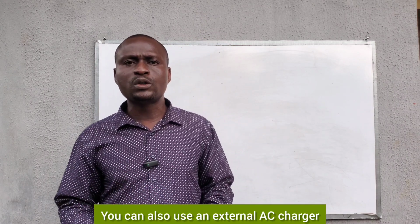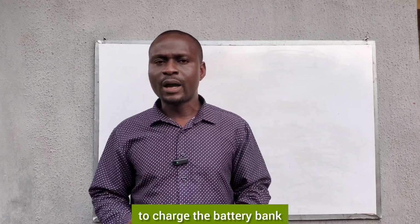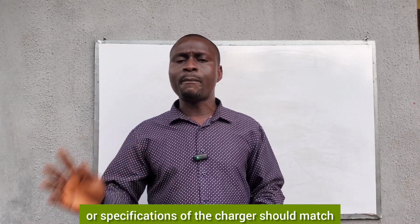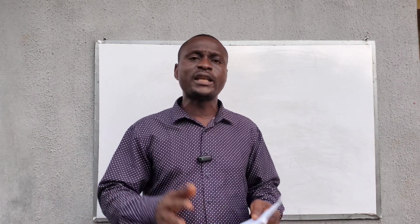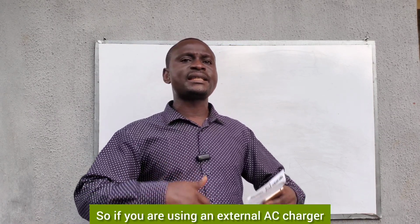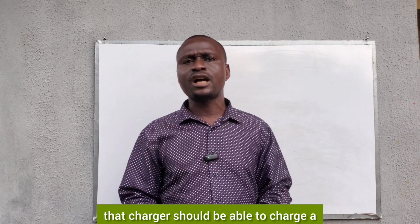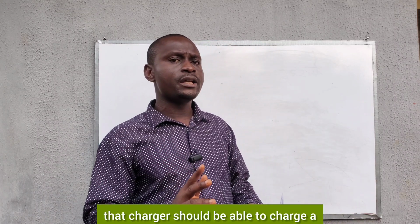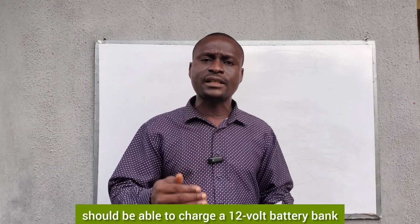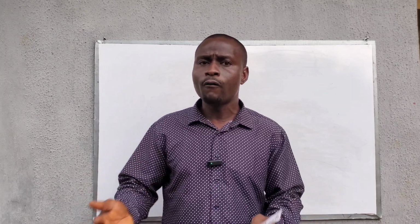You can also use an external AC charger to charge the battery bank, but the parameters or specifications of the charger should match the specifications of your battery bank. So if you are using an external AC charger to charge a 12 volt battery bank, the output charging voltage should be able to charge a 12 volt battery bank, which is about 14.4 volts.